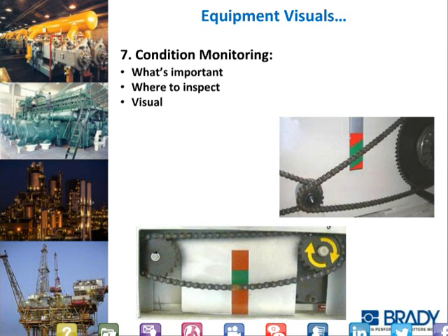The one in the lower center, the arrows show the direction of rotation, and you can see the chain slack is in the green area. That's the allowable slack. If it's in the red, that's either too slack if it's down below, or I don't know how to get up in the red above, because that's over tight and the shafts will be out of position. The other diagram shows the chain slack on the top side, and you can see it's in the green. And again, these are labels that were just custom printed and attached to the machine.